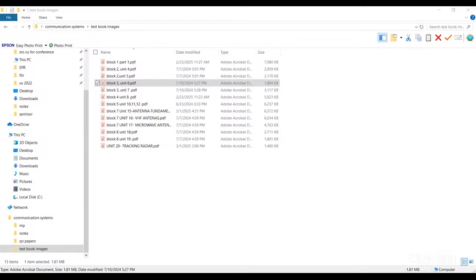The forward waves in the secondary waveguide may pass towards port 4, or may come backward. Suppose it is passing towards port 4, at that time port 3 is 0. Suppose it is passing in the backward direction, at that time port 4 is 0. The wave comes down, going either this side or this side. If it goes towards port 3, port 4 is 0. If it is going towards port 4, port 3 equals 0. This is about the two-hole directional coupler.